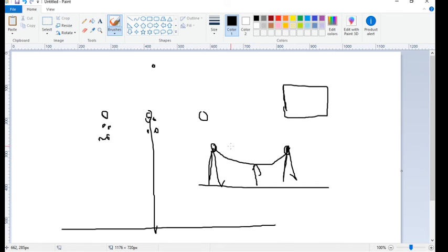I'm sorry. Yeah, so for all 13 conductors you need to specify these dimensions, like the tower height at the tower, the height it's located at, and when it is in the middle somewhere it will be lower, isn't it? So for example, see why I'm specifying, because maybe it may not be really required to take another session specially for this, so just to indicate to you, fine. So this is the R phase conductor, but when you see in mid it will be somewhere here at this height, fine. Earlier it was here, now it is here. So you need to specify all those kinds of configurations.